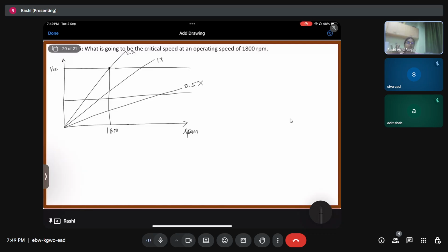So we usually use dimensions which have some tolerances. Because of those tolerances, there may be some eccentricity or unbalance in the system. We have already studied that this kind of imbalance in a rotating system causes unbalanced rotations, and because of the unbalanced masses, we get vibrations.